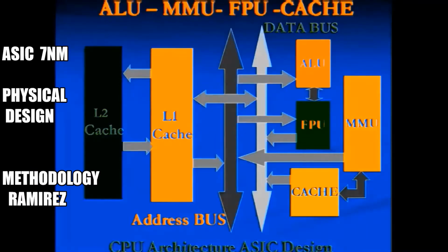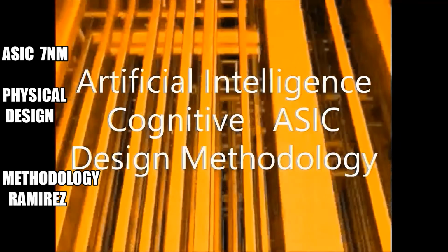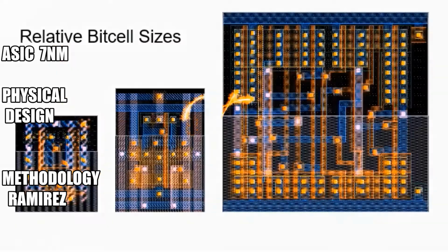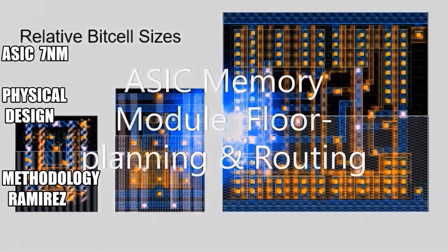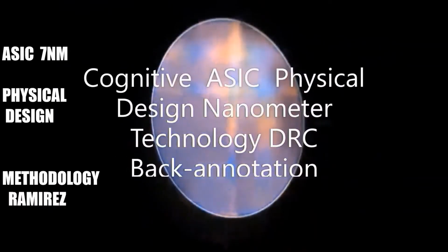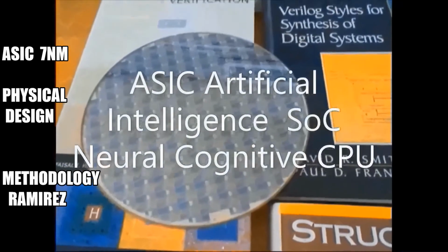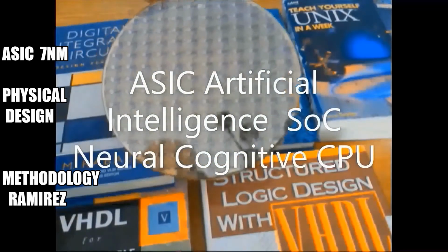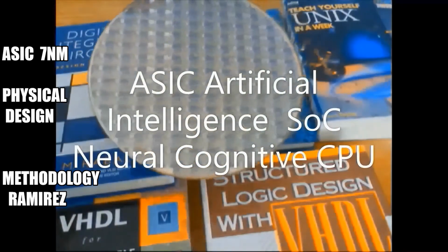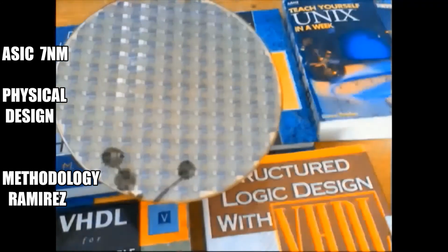On the backend mode, it generates the SPICE models with layout views and timing models to perform DRC and LVS. It can perform at each level of hierarchy or at the end of the hierarchy, and simulates power delay, and it can also be back annotated.